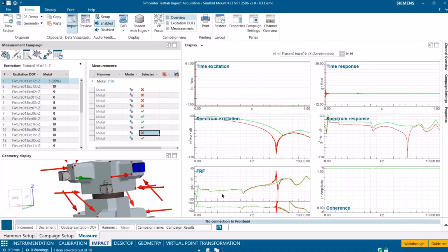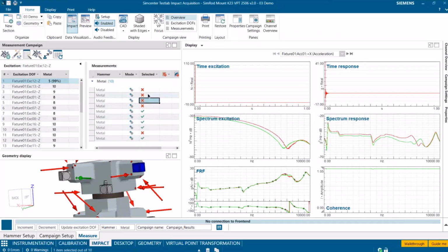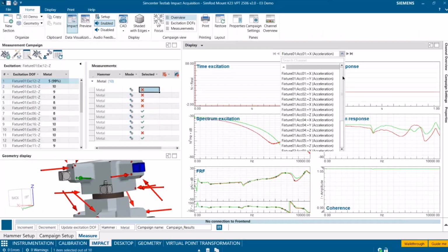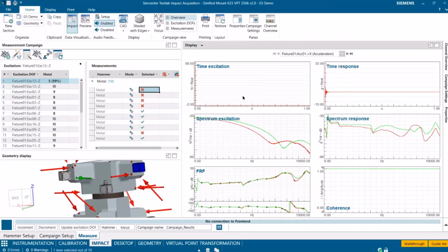Also in the everest data, you can see the average result in green, and then around this anti-resonance on the excitation spectrum, you have quite bad data quality for that measurement, so it gets excluded. We're doing this for 1 point, but this algorithm is actually working automatically across all the response points of the measurements. This is something that you would never be able to do as quickly by hand as letting the computer essentially figure it out.